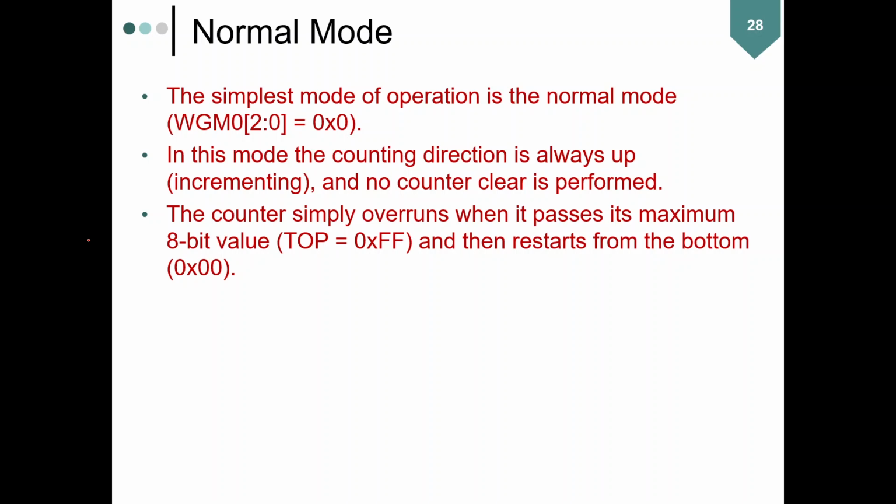In the normal mode, which is the simplest mode of operation, the waveform generation mode bits 0, 1, and 2 are set to all zeros. In this mode, the counting direction is always up, incrementing, and no counter clear is performed.